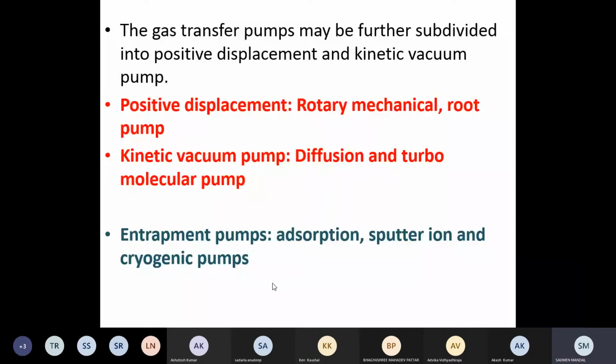So how will you do it? The simple way is that you can do AFM, and along with it you can do EDS, energy dispersive spectroscopy. From EDS you can get what elements are there and their atomic percentage. A similar thing you can get in XPS, photoemission spectroscopy. These are called elemental analysis.